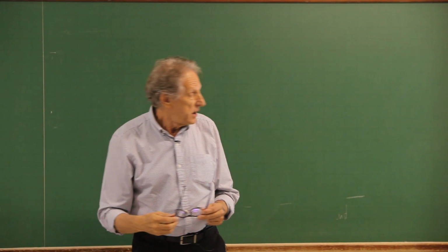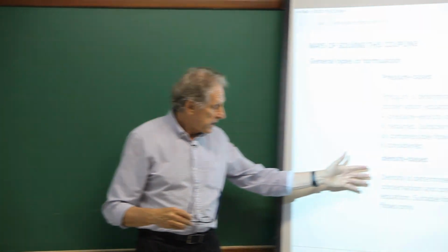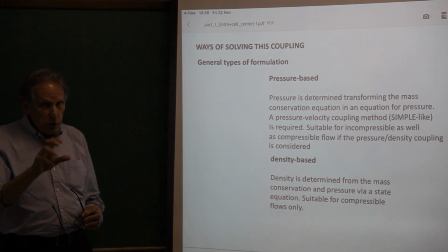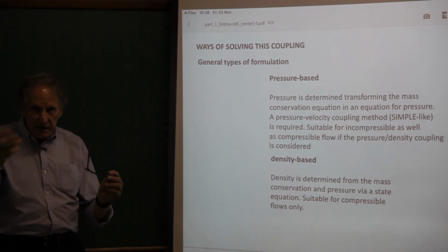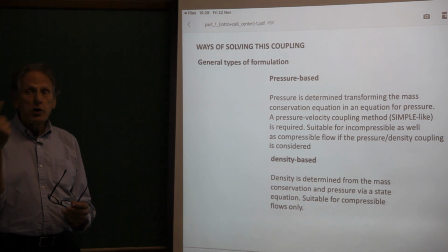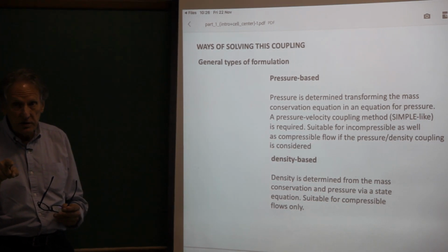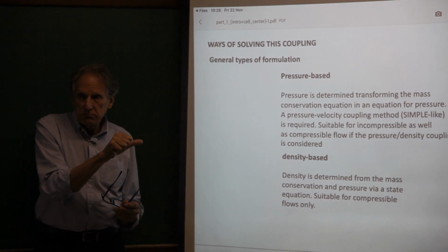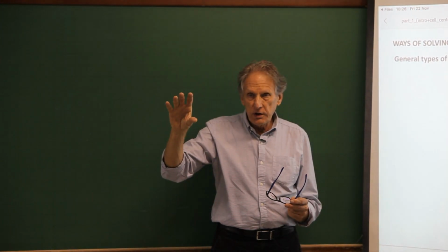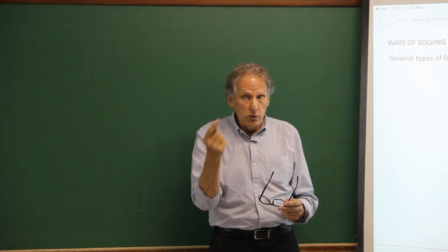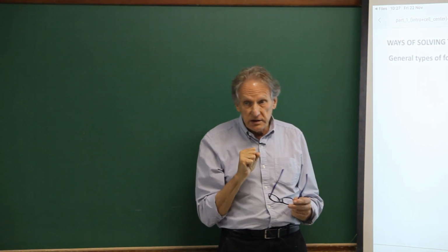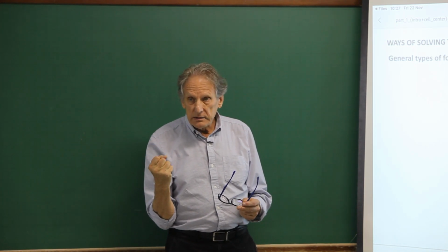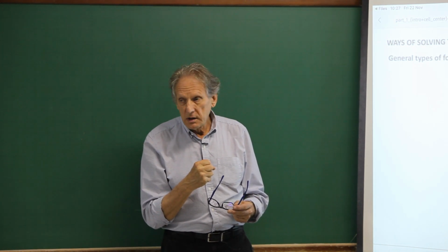And the density-based one uses the natural appearance of the mass conservation equation for solving for density. Then you have the mass conservation equation, density is there, you use it to get the density, and the pressure is obtained through an equation of state.